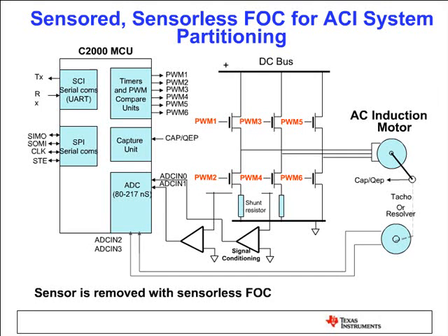So A and B pulses help us to calculate the position, and the index pulse resets the counter each time. Again, incremental encoders are used for precise applications, and capture pins are used for low-cost applications, especially for induction motor. Very low count encoders or tachometers are good enough, and the capture can easily calculate the time in between 2 pulses and convert it to speed.